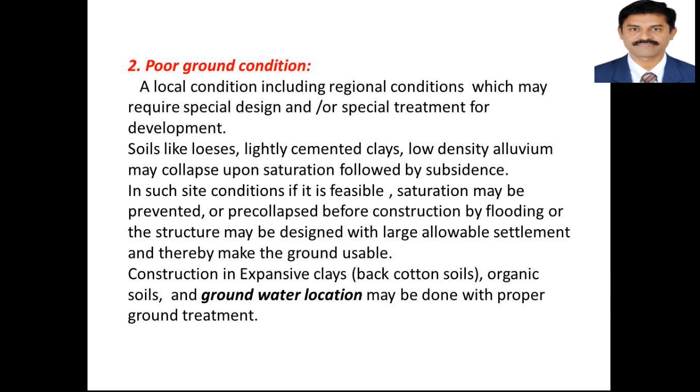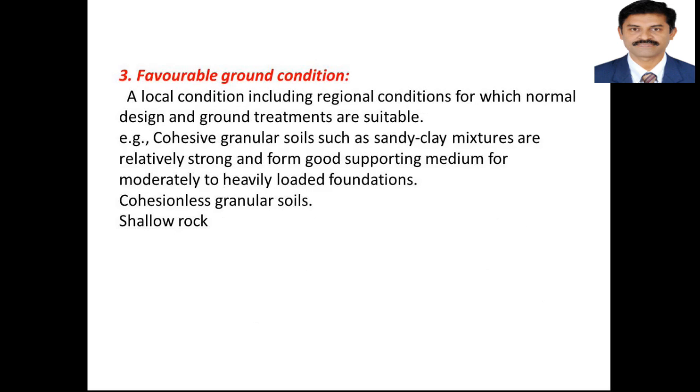Next is poor ground condition, like ground subsidence areas, waterlogged areas. Groundwater conditions are very poor, which may severely affect the foundation soil. Expansive soils are available in the foundation. So those areas are considered as poor ground condition areas. Next one is favorable ground condition, where there is shallow rock, cohesionless granular soils. All those soils can withstand the foundation loading. So, such ground conditions are considered as favorable ground conditions.